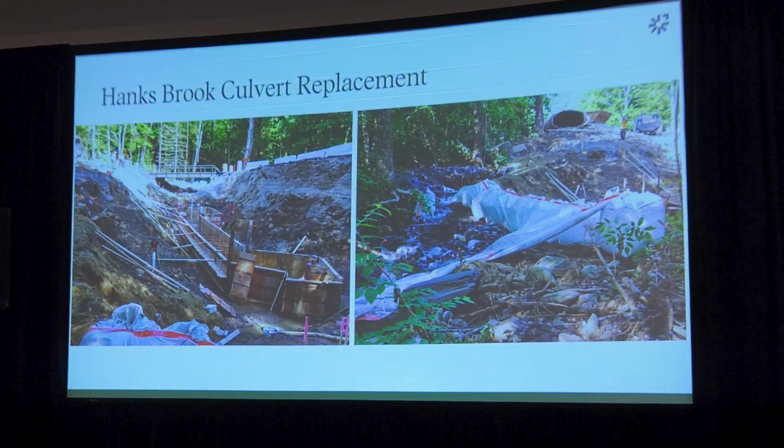I wanted to include a culvert example in here. This was a culvert replacement in Warren, Vermont on Lincoln Gap Road a few years ago. Here you can see they're laying their forms, preparing to pour the concrete for the footing, and they're using sandbags and plastic, it's hard to see, on the upstream end, blocking the flow of water, and they actually have, it's kind of buried here, a bypass culvert discharging on the downstream end around the site, as well as pumping water that would seep into their active work area while they were working to keep it as dry as possible.